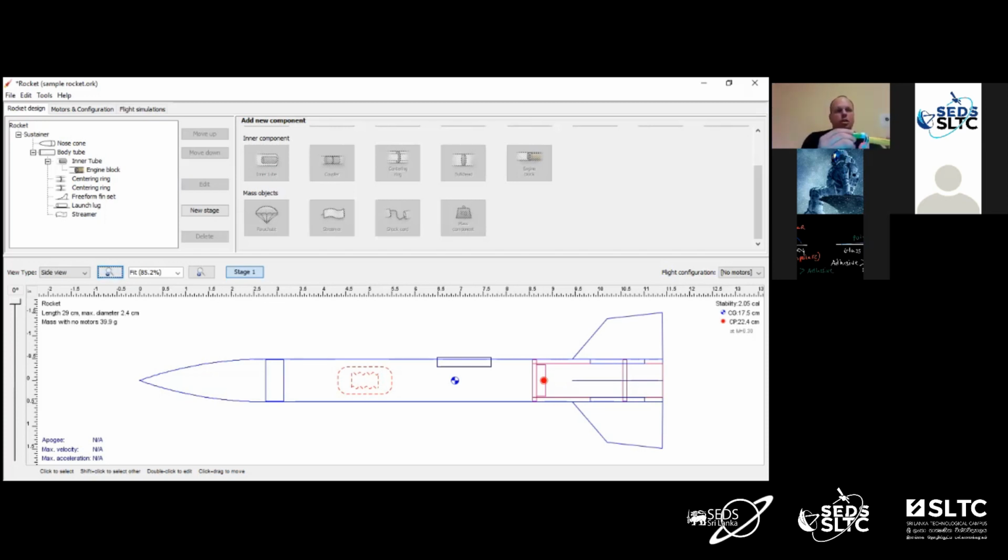So when this is all assembled in flight, it reaches its maximum altitude, and then we need to get the recovery device out. So this little explosive ejection charge fires. It's going to blow the nose cone off and push the streamer out. And so this, what we call the shock cord, which is this band here, gives it a way for the energy of the nose cone flying out to dissipate a little bit and not just rip the whole thing apart. So again, this is called the shock cord. Let's add that in.